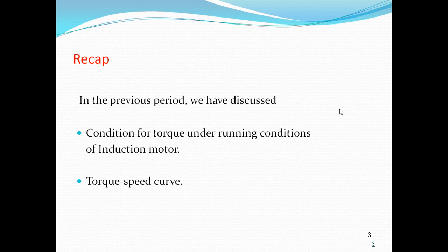Torque increases and reaches its maximum value when slip s is equal to R2 by X2. This maximum torque is also known as pull-out torque or breakdown torque.